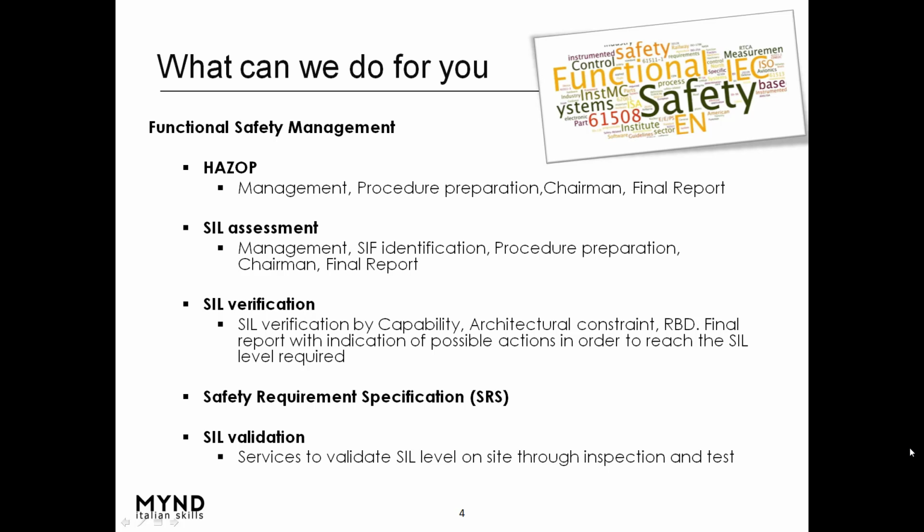But important that we can draw up the final report with indication of possible technical intervention in order to reach the required SIL level. For example, it could be an idea to increase or decrease the test time, or to make the instruments redundant, or even to make the solenoids inside the valve redundant, all to respect the minimum required SIL.